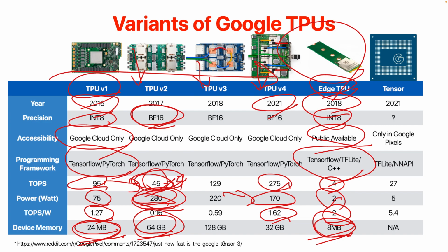This expansion board has a heat sink, and under this heat sink, they have a chip. That chip contains both CPUs and GPU. And the level of CPUs and GPUs it provides is pretty close to the ones that are used in the Nintendo Switch. So that's one fun fact. Okay, so this is the CPU and GPU complex. And under this, there is a circuit board here. You can consider this as a motherboard, so it does have some interconnects.